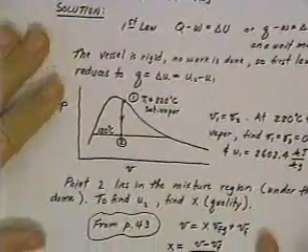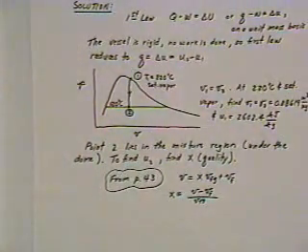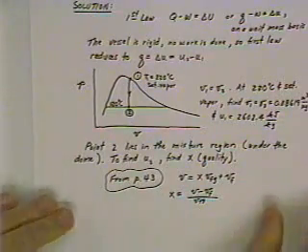All right, so if we go back now, we calculate the X. Knowing X, we have to calculate that from V is equal to VF over VFG. We have that information now that we've just pulled off the steam tables.